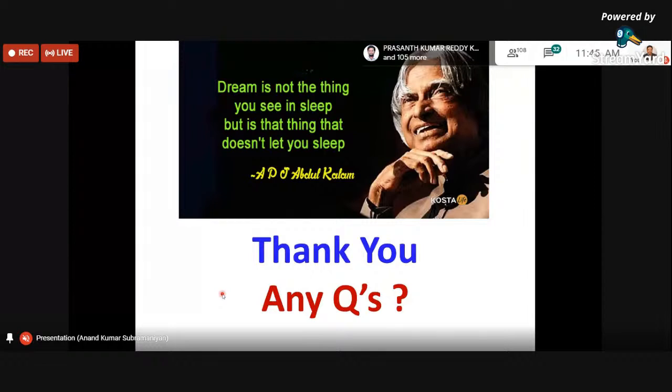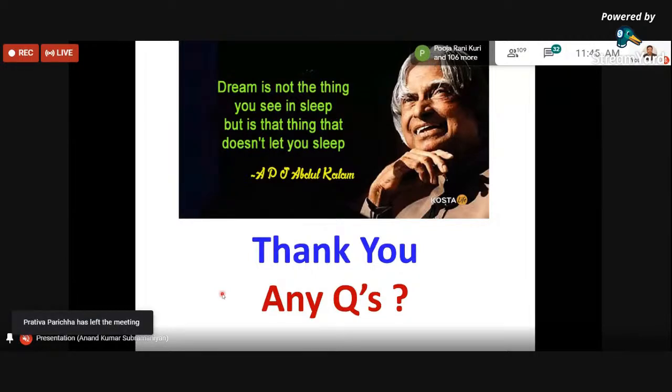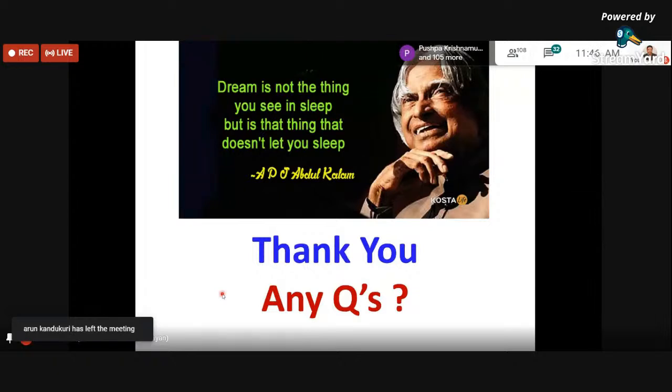be removed. Otherwise, the presence of such rough features will be detrimental for fatigue performance, because we know that fatigue has a strong correlation with surface roughness. If you have higher surface roughness, your fatigue life will be less. So what I'm trying to say is that we need to go for post-processing after the SMAT process.